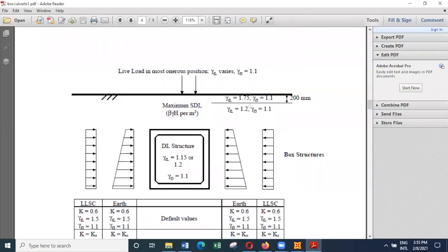Here you have to get 1.2 multiplied by 1.1 multiplied by the beta factor, which is 1.15. So you get 1.15 multiplied by 1.2 multiplied by 1.1. So here also you should get 1.15 into the sum, which is 1.75 multiplied by 1.1 multiplied by 1.15. So altogether 2.21.